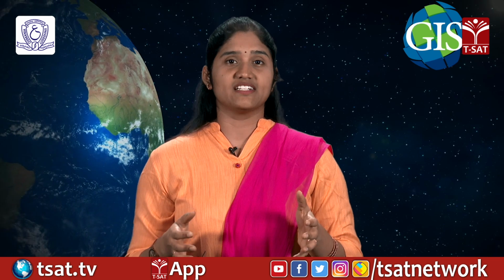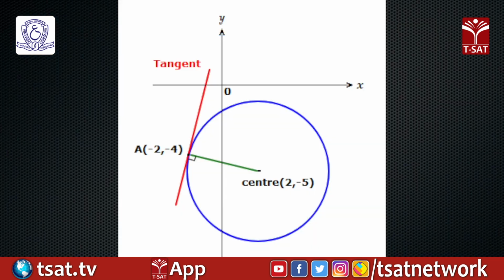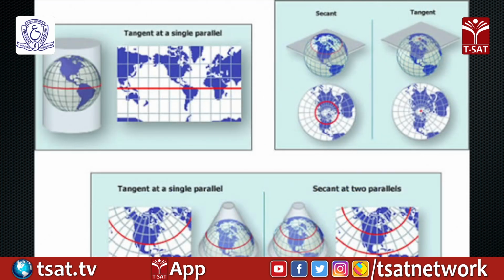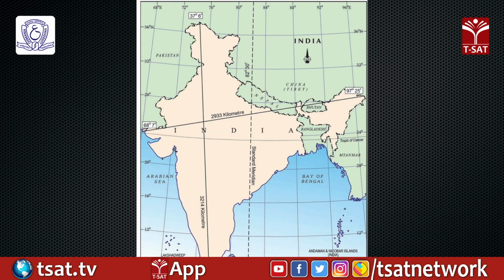Map projection parameters. The concept of case relates directly to the standard line, a common parameter in defining a map projection. A standard line refers to a line of tangency between the projection surface and the reference globe. For cylindrical and conic projections, the simple case has one standard line, whereas the secant case has two standard lines. The standard line is called the standard parallel if it follows a parallel, and the standard meridian if it follows a meridian.